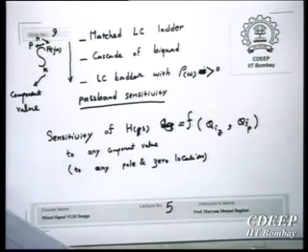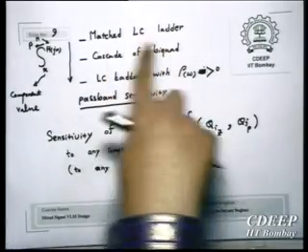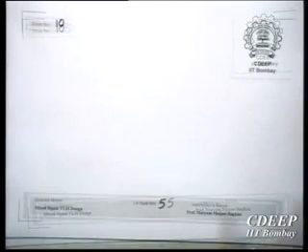So now, what are other ways we can implement a filter, to get the advantage of the small rho of a matched LC ladder? This is something similar to what your friend said. Right now we know two methods: a straightforward cascade of biquads, and the LC ladder, whose property comes from the multiple feedbacks inherent in the structure of the filter.